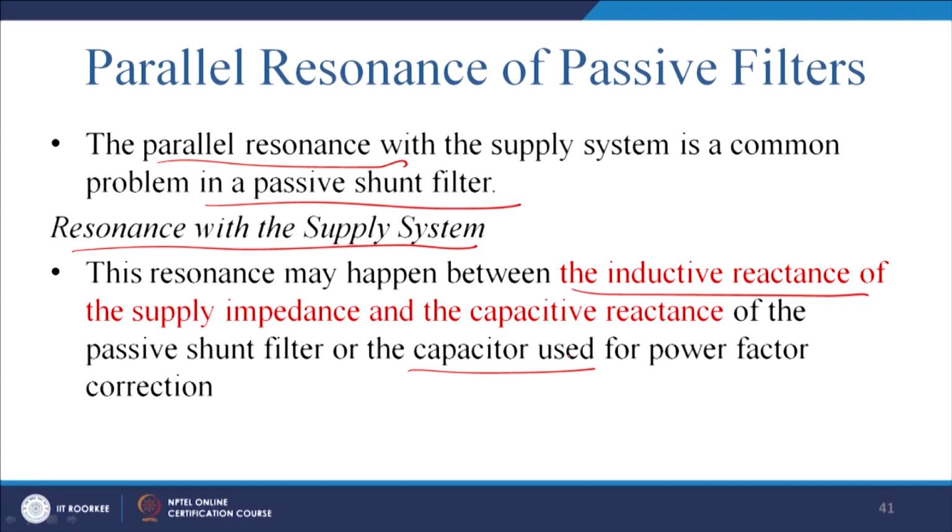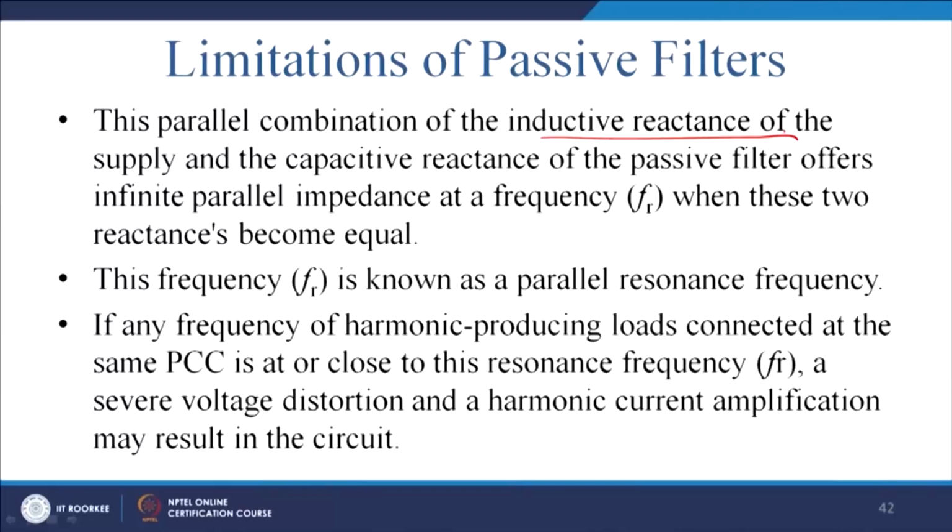So, this is also one of the elements that will give you problems in GATE and in assignments, and you will see how detrimental it is. And moreover, the parallel combination of the inductive reactance of the supply and the capacitive reactance of the passive filters offers infinite parallel impedance, which is also very detrimental, at the frequency fr when these two reactances become equal.